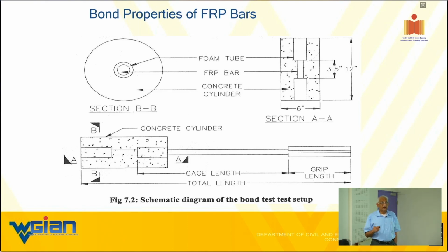So the ASTM calls for, again, when I say 40, maybe 42, 38, it really doesn't matter, but it has to be in that range. And in that regard, a very important point is that if I do not create adequate compression of the grips in the perpendicular direction to the length of the grip, it would slip.